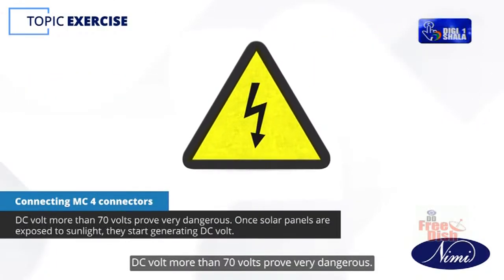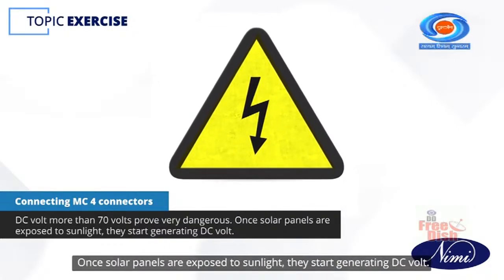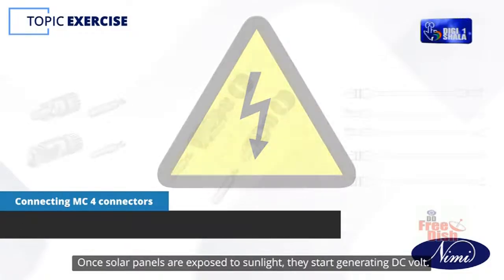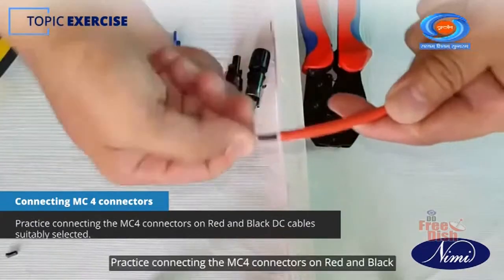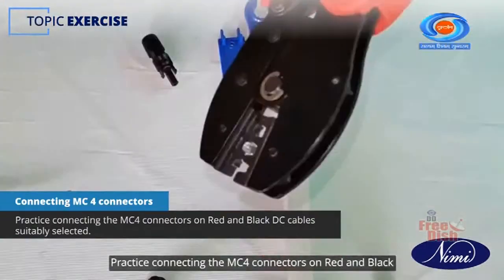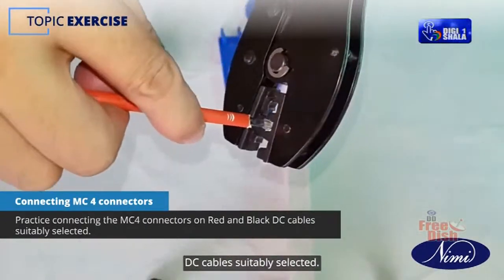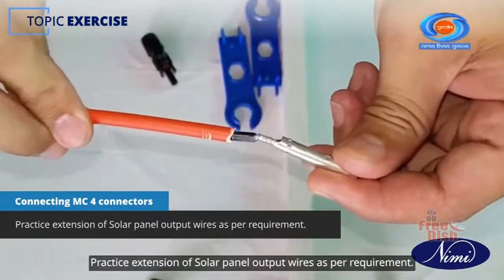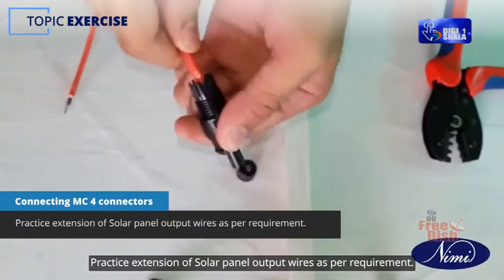DC voltage of more than 70 volts is very dangerous. Once solar panels are exposed to sunlight, they start generating DC voltage. Study the pictures to familiarize yourself with the assembly parts of MC4 connectors. Practice connecting the MC4 connectors on red and black DC cables suitably selected. Practice extension of solar panel output wires as per requirement.